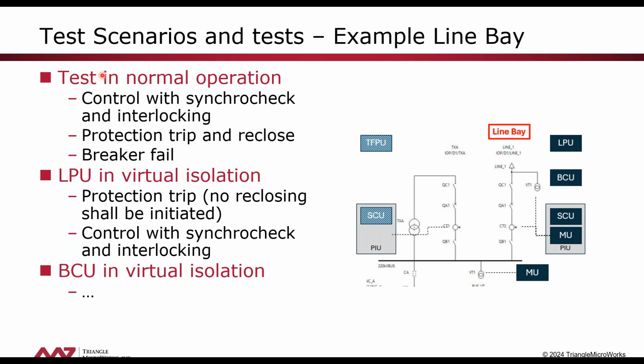The tests that we specified did not only include tests in normal operation. For the line bay, the tests in normal operation would be a control with synchro check and interlocking, protection trip and reclose, and breaker fail.